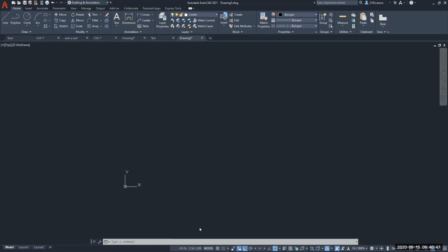So if I hit save as, it saves it as a drawing, but you can reuse the template. Yeah. The moment that you move it out of the template folder, it will automatically change it to a DWG. Like when you went into your file folder to save it in 110 drawings, that's when it changed it to a DWG, because it knows that it's no longer a template. Because it's not in the template folder anymore. Right. Correct. But you just verify that it changes it to a DWG. It does it for me automatically, just like it did for you.